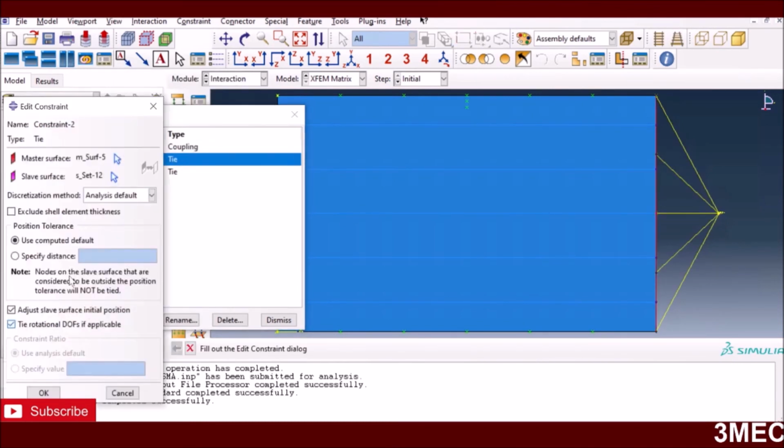Second thing is how to tell ABAQUS that these fibers are connected with this surface, or that they are inside the material. So I use a tie constraint, which is the easiest way of doing it. I select all these nodes of the fiber. You can create a node set by removing the matrix and creating a node set for the fibers on this side, and then for the nodes on this side for the fibers, and then you select those as master or slave, and then you select this surface of the matrix as one of the surfaces.